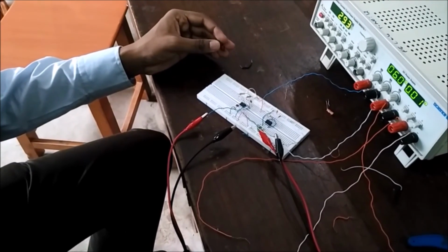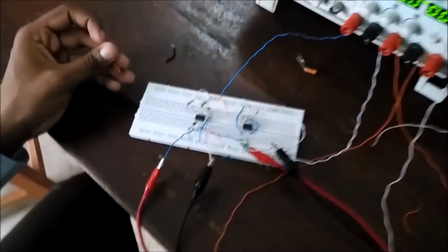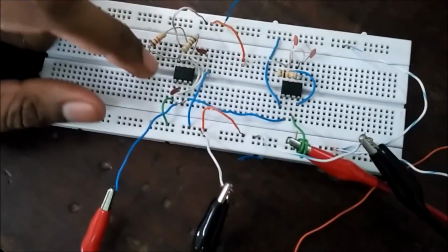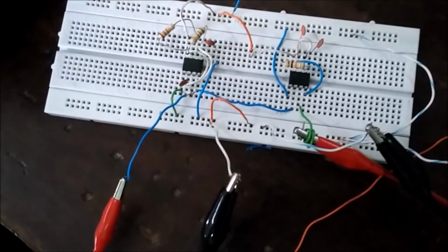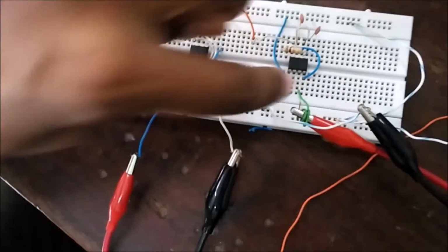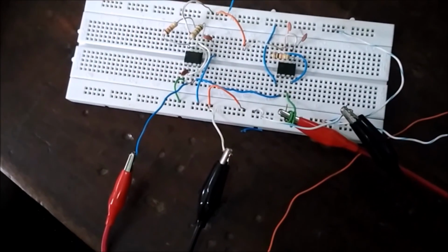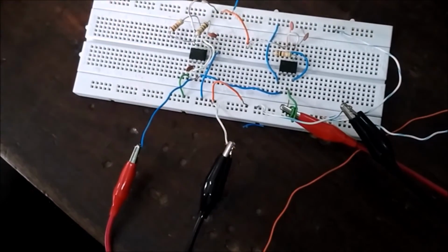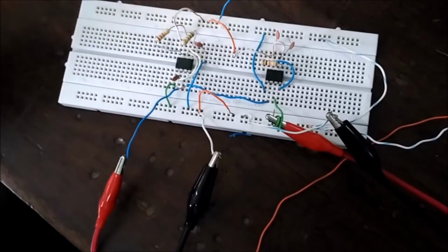This is the monostable multivibrator circuit. For the trigger, we have used an astable multivibrator circuit of duty cycle 90%. The circuit has been made according to the circuit diagram, and the standard resistors and capacitors have been used as shown in the design data. The output of the astable multivibrator is given to the trigger input of the monostable multivibrator. Now moving on to the DSO to check the waveform.